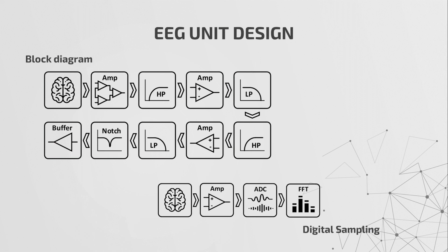According to design, we have used a general-purpose instrumentation amplifier chip like AD620AN. In this primary stage, the gain is 100. After that, multiple stages of amplification are required to amplify the signal. We have used additional two separate stages of amplification. Gain in each stage is 100.